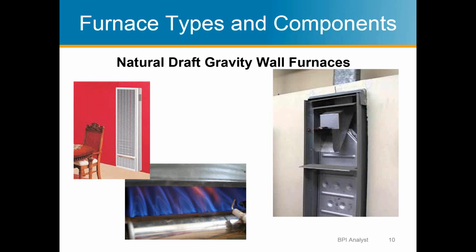There's another question about gravity furnace. One of the audience members had an old gravity furnace, and is that the same as a natural draft furnace? Well, similar terms. A lot of times it may depend on where you're at and just how the local people call it. But most of the time, a gravity furnace, we would call it a gravity wall furnace or just a wall furnace, but yes, they're typically natural draft.